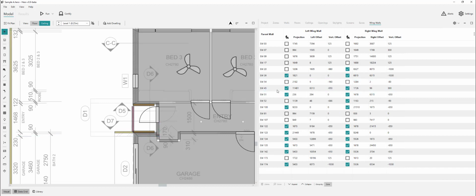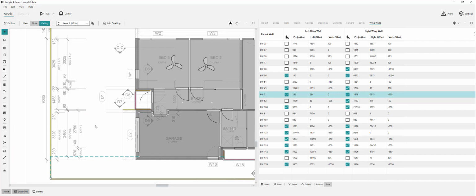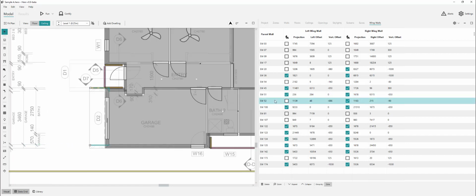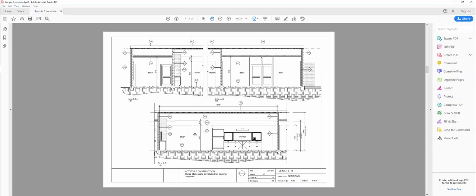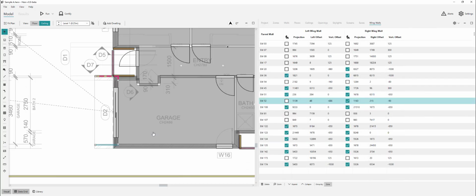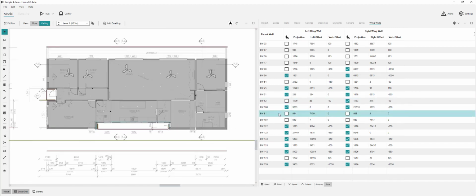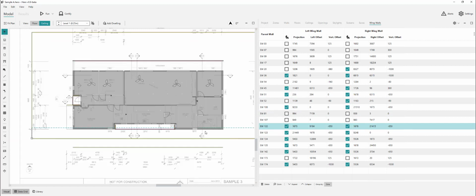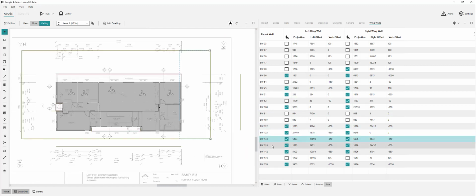That wall here is going up. It has the vertical offset fine. South wall of the garage looks fine. This left wing wall here, the dimension needs to get picked up. 2310 is its height, so it's -90 on the left, similar to how it is on the right. These fence heights all look fine, the wing walls caused by the fences and the northern walls there. Okay, so we've now modelled the wing walls correctly. Their heights have been modelled as the main object of the data grid entry for those.